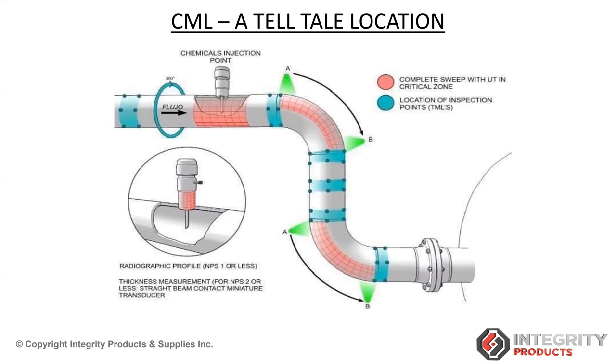This is the picture showing the recommended locations where we need to conduct radiography or ultrasonic thickness measurement, considering the location of the chemical injection. And also, an interesting thing with inhibitors is that there have been inhibitors in the market called filming inhibitors.